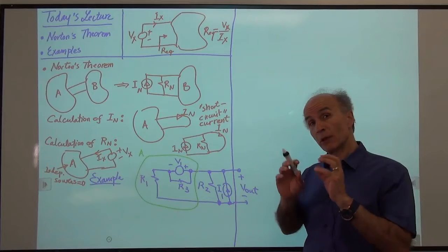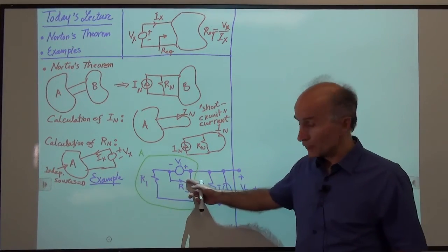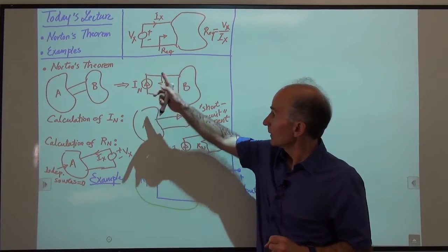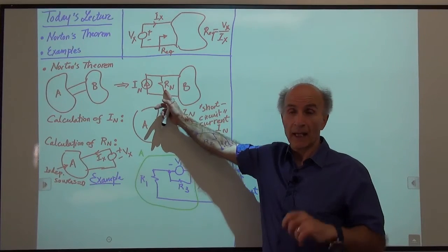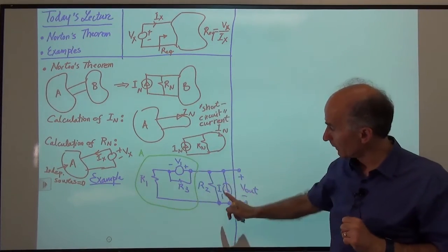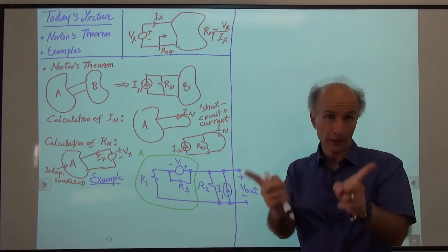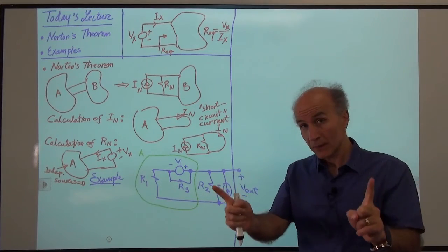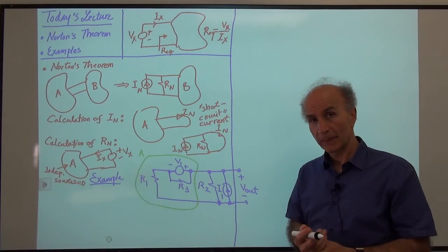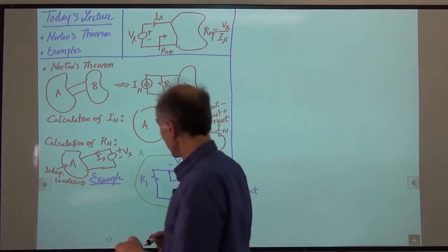The calculations will probably be simpler. But even if you want to really optimize things, we say if this is reduced to a Norton equivalent, then it will be a current source in parallel with a resistor. And that's such a fortunate coincidence, because now those two will be parallel to this resistor and this current source. If two resistors are in parallel, we know how to handle them. If two current sources are in parallel, that's great, they add up. So again, we know how to handle them. So maybe we should go with the Norton equivalent. Okay, so let's go ahead and do that.